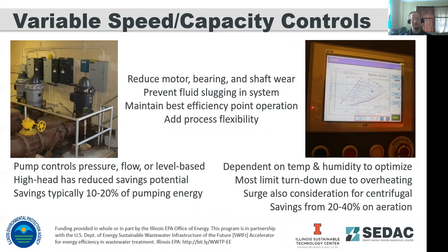And if you add a VFD to pumping systems and aeration systems, you're better able to maintain operation closer to the best efficiency point operation of those pumps and aeration systems.